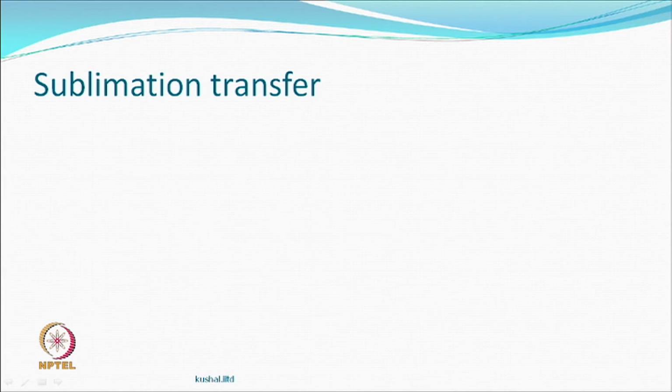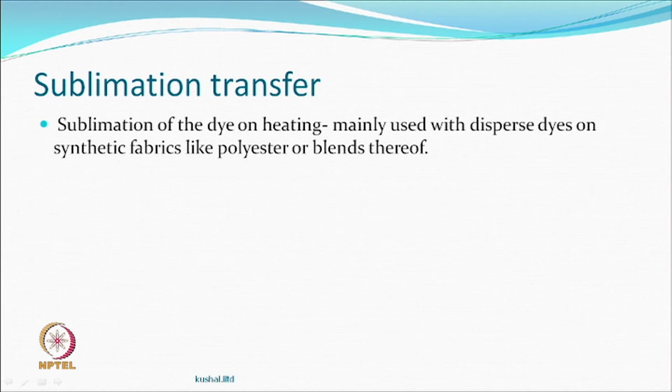The dye and substrate combination is an important part. Every dye that you have seen and used cannot sublime. So, every material or substrate that you see may not like the dye that sublimes, and so you have to have the right combination. Now, the right combination comes with a class of dye which we know as a disperse dye and synthetic fabrics like polyesters. This is almost like a made-for-each-other situation.